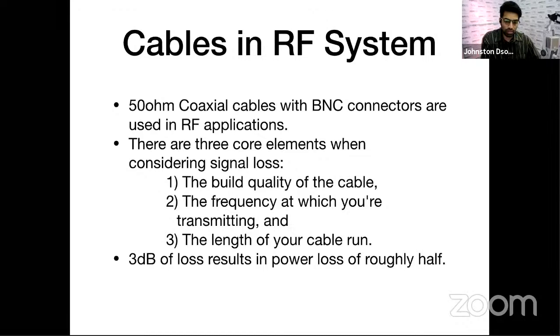Coming to the last part, at least on the slides, and then there are a couple of things which I'll tell you without slides, is cables. Okay, we do not really think about cables because these BNC cables all look the same, so we don't bother. But the thing is, there are grades of BNC cables also. The grades that we use in RF are RG58 and RG213.